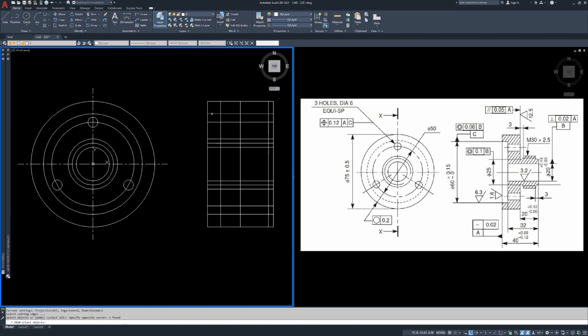So that means we want to pick this top edge and this bottom edge. Right click, trim that out. Now you're probably saying, Danny, that line is actually there. This is inset. So this inner circle is bored out of this part. So yes, you would see that line, but it would be fainter because it's not in the foreground. It's actually in the background.